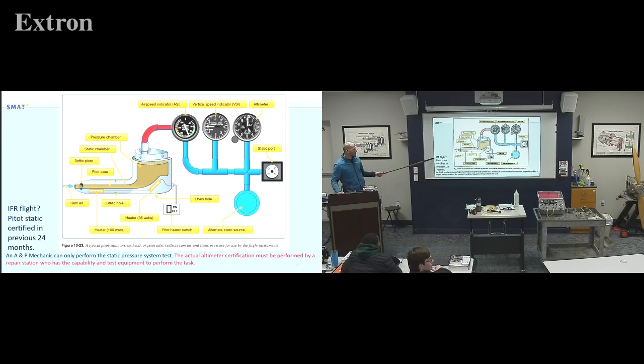IFR flight, we talked a little bit about yesterday. The system, and there are 3 things that have to be certified within the previous 24 months, and that's always that fun question, right? So if it's certified on June 5th, you have until 24 months plus the end of June to have it certified again. So if it was certified June 5th, 2023, we're basically good until July 1st, 2025.